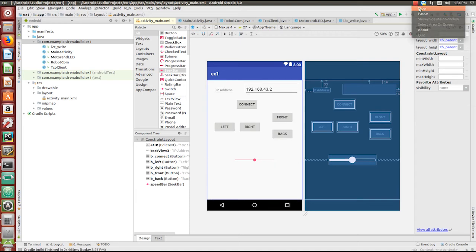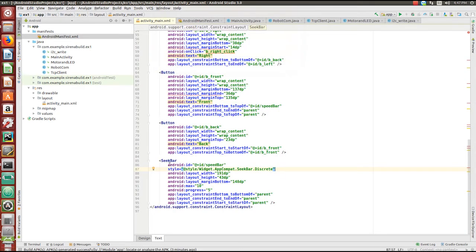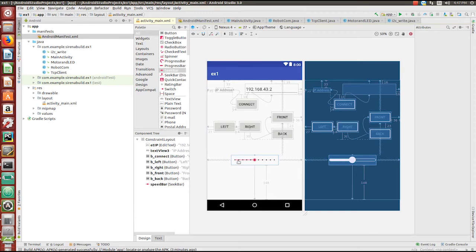So we're going to get our speed. A couple of changes we need to make now are, in the seek bar, let's set the style as discrete. This way your seek bar starts looking like this, so you cannot really choose intermediate points, but at the same time the response of the seek bar stops because it's discrete. It does not flush a lot of values to the Wi-Fi, so it's more efficient to use a discrete value instead of a continuous value, in which case you'll keep getting a new callback and every time you'll keep releasing a new TCP/IP message to your controller.